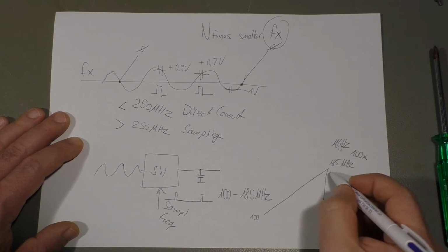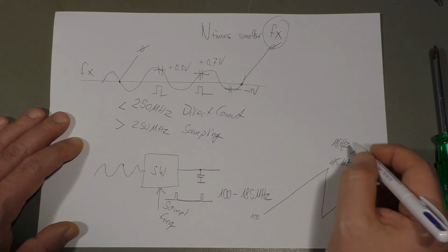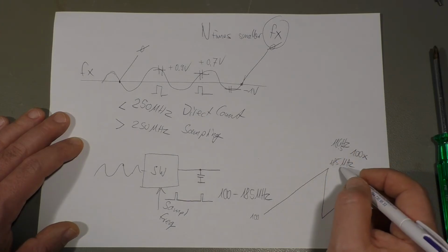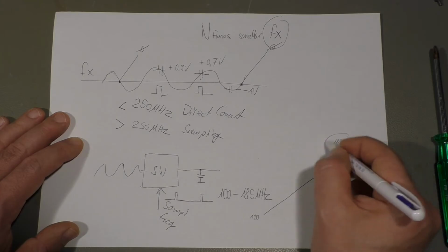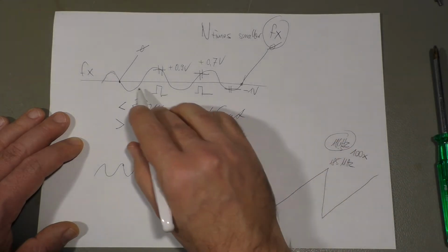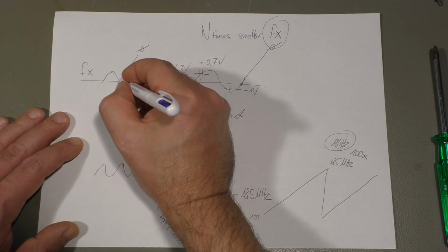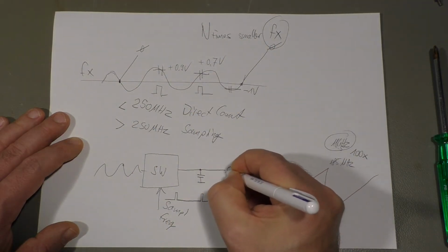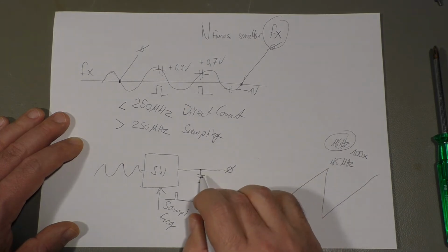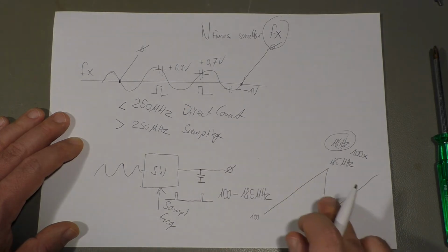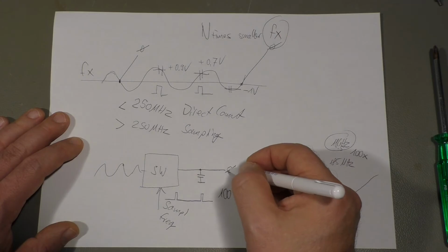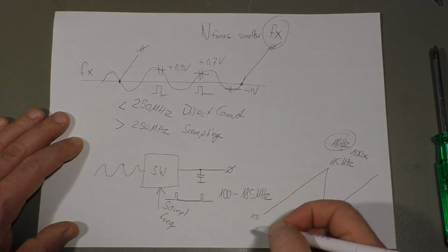So that means you sample the maximum frequency with a sampling frequency that is 100 times slower than the 18 gigahertz. If you get 0 here, or at the output of this you also get 0, then you know your sampling frequency is phase locked to the input frequency.